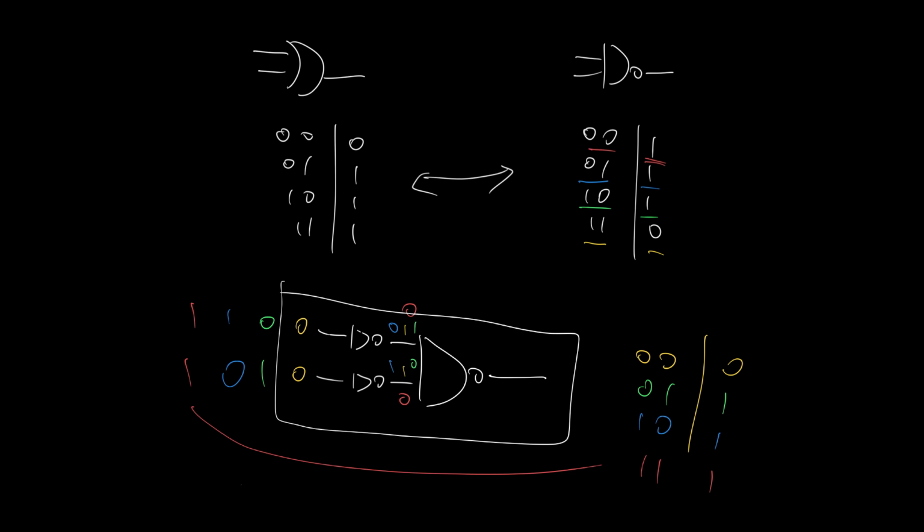If we want only NAND gates, then of course we just replace each inverter with an inverter made using a single NAND gate like we learnt before. So in other words, the answer is that our circuit looks like this. That is an OR gate.